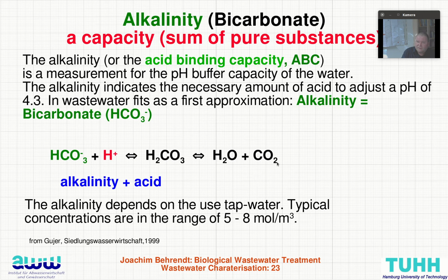Besides these interesting components, we have other candidates which are important for wastewater treatment. One is the alkalinity. This means the concentration of bicarbonate. This is a capacity sum parameter. Alkalinity means the binding capacity for acid. This measures the pH buffer capacity of the water.